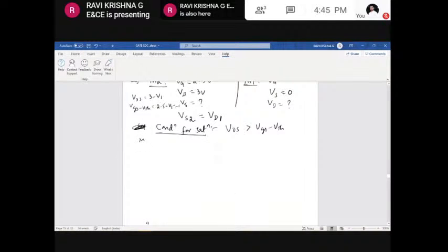So for the transistor M2, VDS is on one side, and let's write VGS minus VTH on the other side. Now let us verify whether VDS is greater than VGS minus VTH for the saturation region. Here VDS is 3 minus the source voltage, but we don't know that source voltage. The gate to source potential will be 2.5 volts minus Vs minus 1.